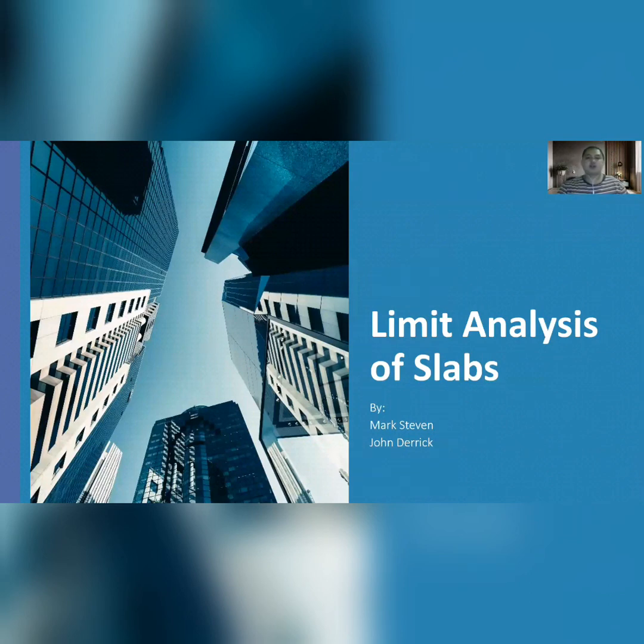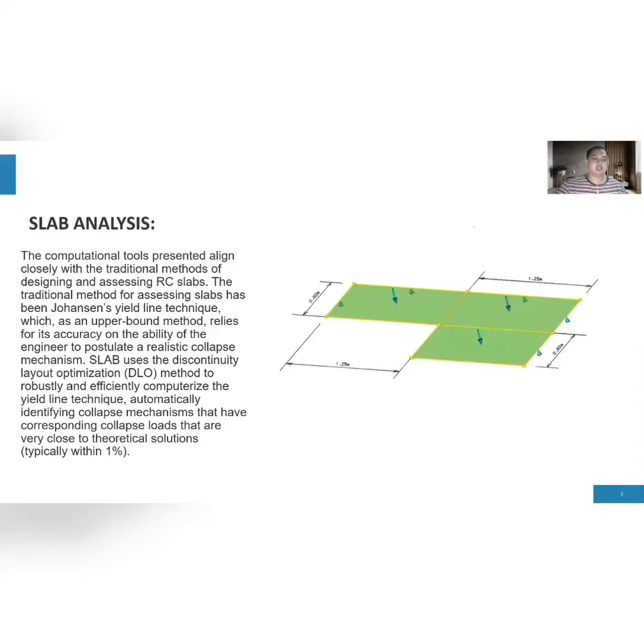We are reporter number 4 and our topic is limit analysis of slabs. So, ano nga ba yung limit analysis of slabs? The computational tools presented align closely with the traditional method of designing and assessing RC slabs. The traditional method for assessing slabs has been Johansen's yield line technique, which, as an upper bound method, relies for its accuracy on the ability of the engineer to postulate a realistic collapse mechanism.